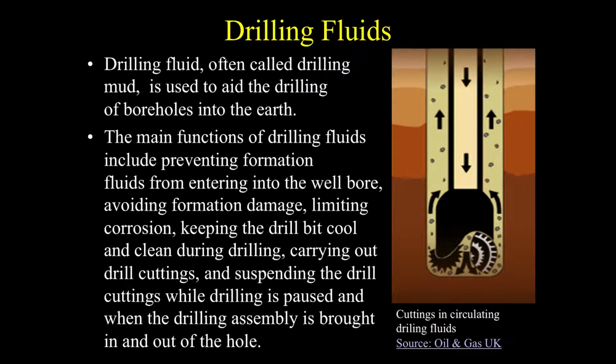During drilling, cuttings are created, but they do not usually pose a problem until drilling stops, because drill bits require replacement. When this happens and drilling fluids are not used, the cuttings then fill the hole again. Drilling fluids are used as a suspension tool to keep this from happening.